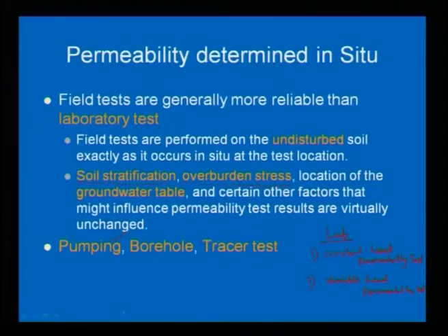We will discuss this, and also the laboratory constant head and variable head permeability tests. Then the borehole test: in the field you make a borehole, allow water to flow inside it, and measure how much water flows with a recorded time. Discharge per time gives velocity, and from there you can find your permeability.